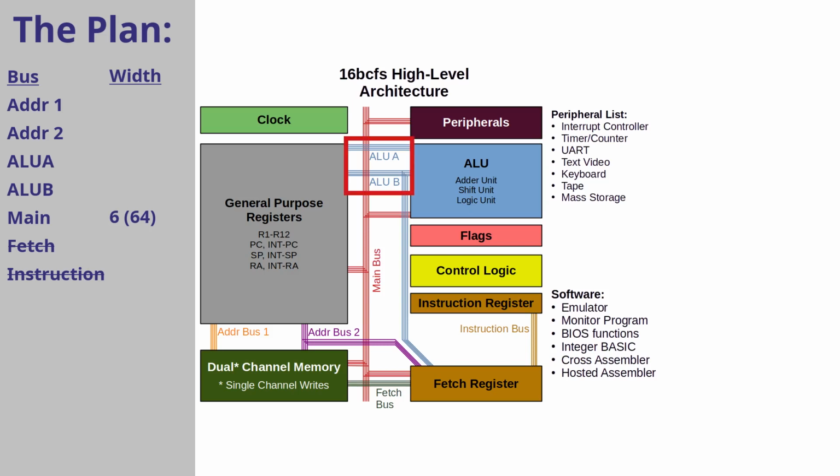Now, ALU A and ALU B, on the other hand, are far more whittled down. ALU B has 1 extra place that has interest. I probably am going to be pushing 16, maybe 18 things that might have interest in pushing out onto those 2 buses. And I'd rather not bump that to 5 bits if I can help it. So I think I'm going to artificially limit those to 4 bits apiece.